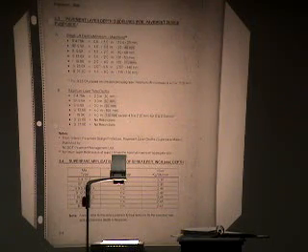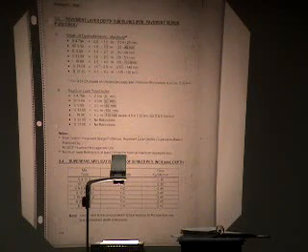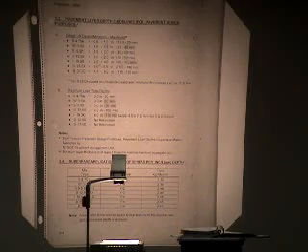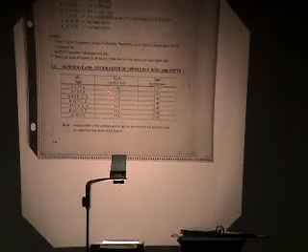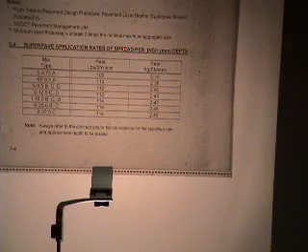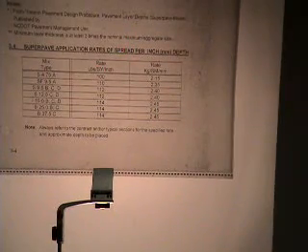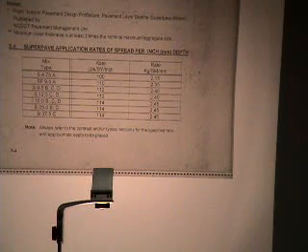I would say they are pretty good guidelines for construction, but you can place mixes thicker or thinner than these numbers indicate here under the right conditions and so on. These are just guidelines that they use when they're developing that typical section. Likewise, down at the bottom, one set of numbers you may be interested in is this column right here. These are the rates in pounds per square yard for 1 inch of depth. Please note, for 1 inch of depth, that are used to compute quantities in contract by NCDOT.